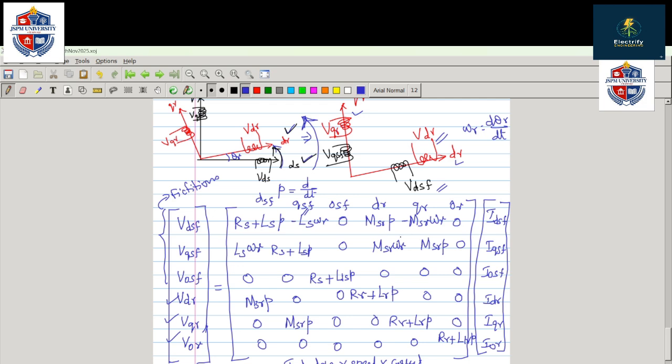From this we can understand the winding equation of three-phase electrical machines in the stator-rotor attached reference frame, where the d axis speed EMF term has a minus sign, since when we transfer the stator variable to the rotor, the d axis component will be lagging compared with the q axis component. That's why we have the minus term.